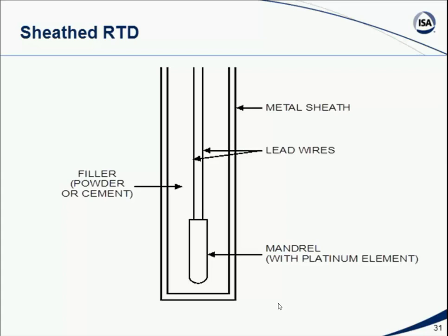It does introduce a little bit of an issue because obviously the RTD itself is not directly in contact with the liquid that we're measuring, for example, the temperature we're measuring. So there is a small time lag, but it's usually a rather small one because we're really not talking about a large physical area here. So it slows response a little bit, but generally that's not much of a problem.